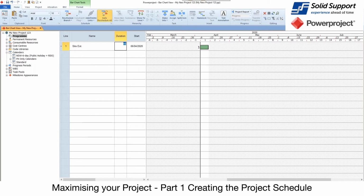Now, I can obviously change that just by typing in different durations, and in days I can just type in the single number. If I say it's 6 days, it's 6 days there, or I might say it's 2 weeks, and I can type in 2 weeks. You'll notice this blue hatch, which you can control the color for, is actually the holiday, so that's a bank holiday that's in there. I might say it's 1 week, 2 days. I can type in any duration you want, and you have weeks, months, years, days, hours, minutes, and for those who might want to, you could go to seconds. We don't have anyone really going down to seconds on here.